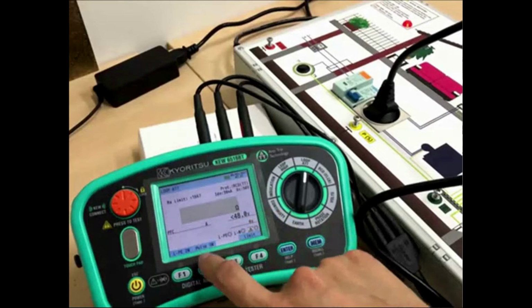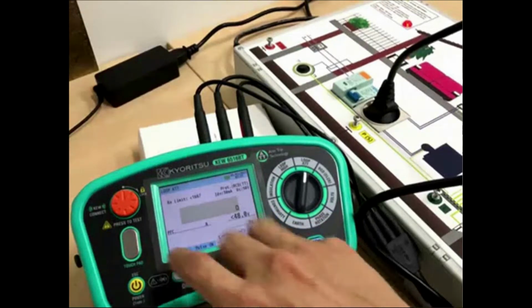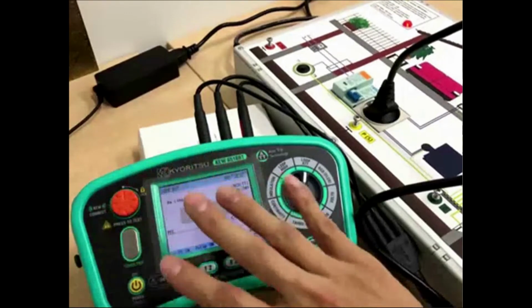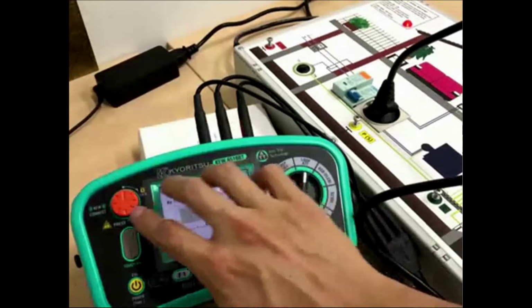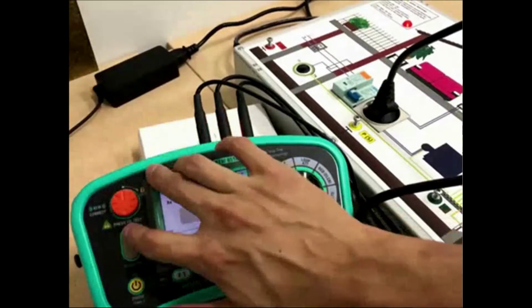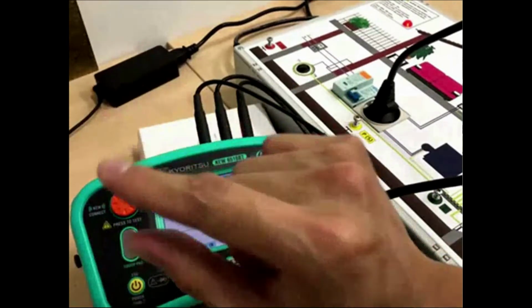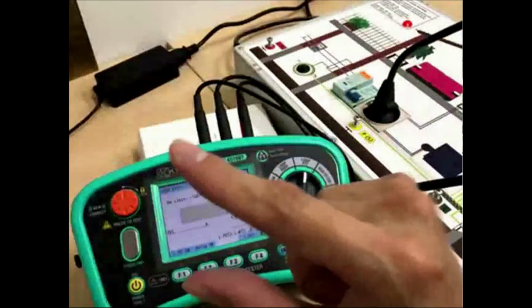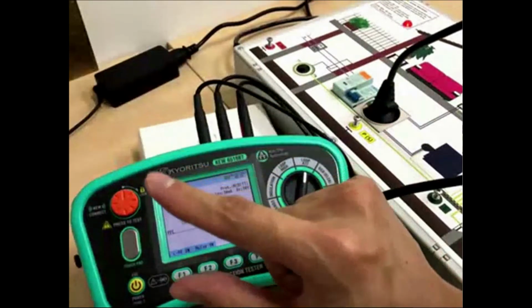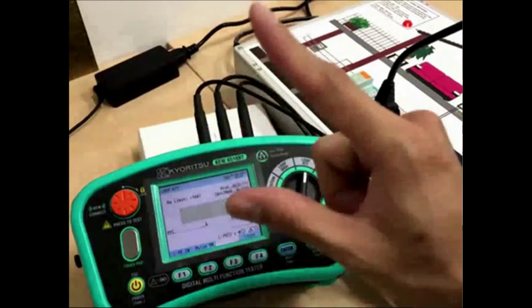The meaning of this pulse on is, before you run the loop test, listen carefully. Before you start to run this test, there is a short burst of high current out to the circuit. It removes the oxidized coating of the circuit to give you a more accurate result.